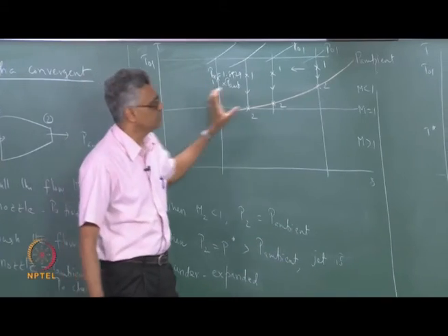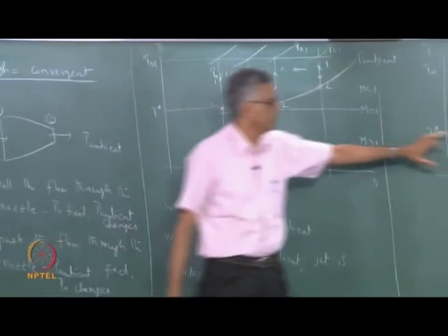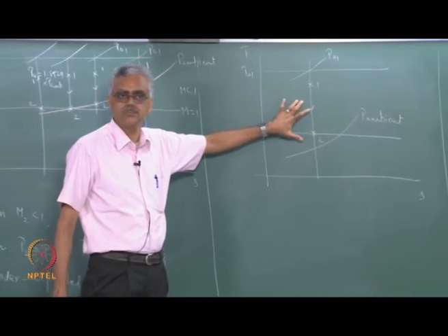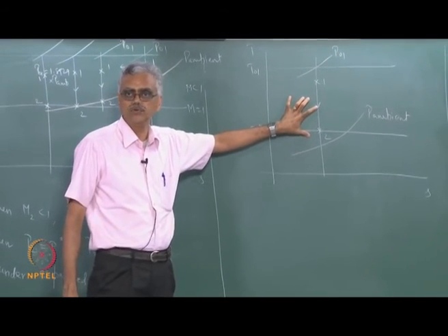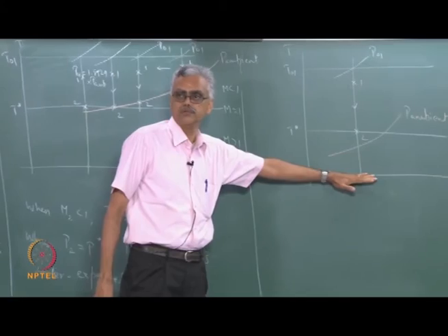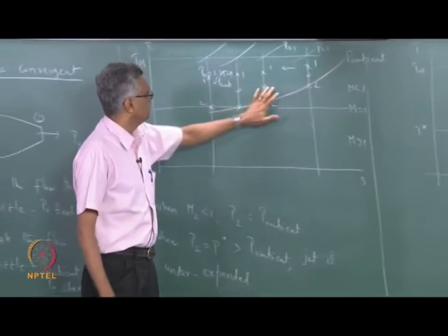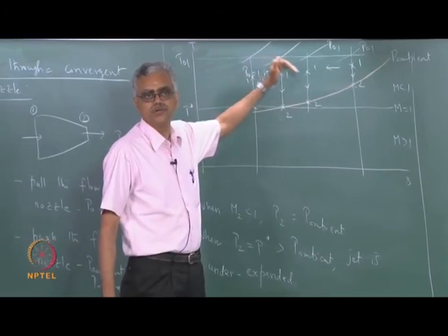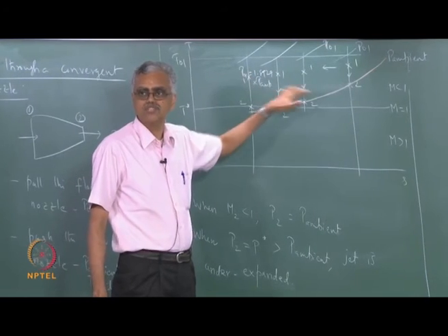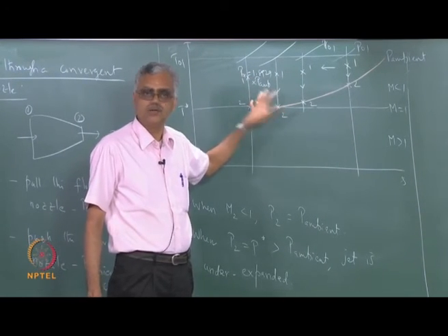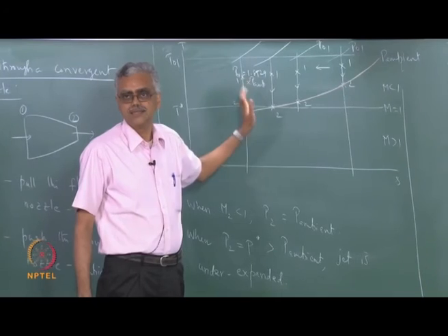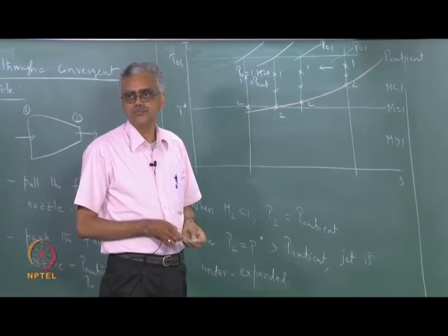That is the biggest difference between this and that. Here, after I attain the critical state, the process curve remains the same, I cannot change it anymore by lowering the ambient pressure. Whereas here I can change the process curve by increasing P0 continuously at will. So mass flow rate can also be changed at will as I keep increasing P0. That is the difference between these two.